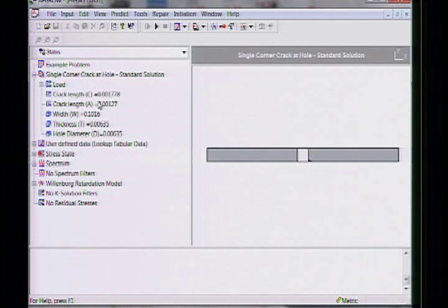And my only answer always to that is, well, you're the guys that say all I got to do is move the decimal point, so just move the decimal point, and that's good enough. So your crack length in AFGROW and metric is always going to be meters, so always consistent. Megapascal, meter, and degrees Kelvin.